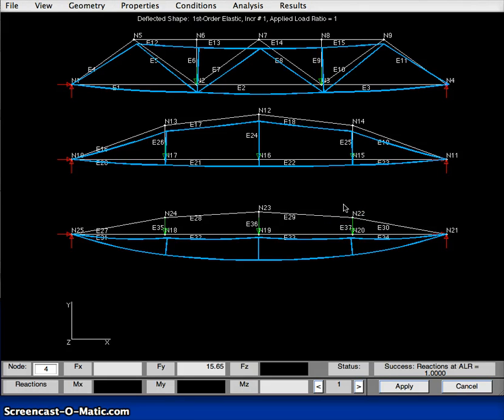Now that we've investigated the behavior of the 3 bridges provided in the homework file, it's time to design our own. To do so, you should first begin by making a careful drawing of your bridge, labeling all of the nodes and elements, and calculating the coordinates in x and y space of each of the nodes. I've already done that, and I'm going to input a design of a fairly simple king post truss bridge, just to illustrate the steps needed to create a working model.